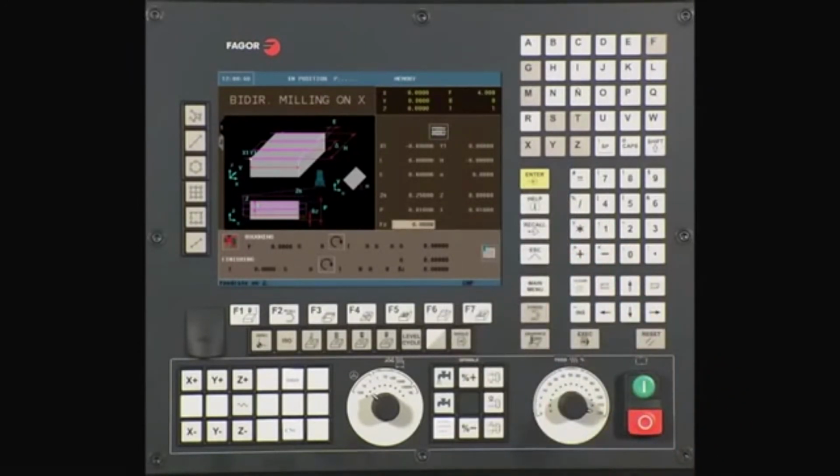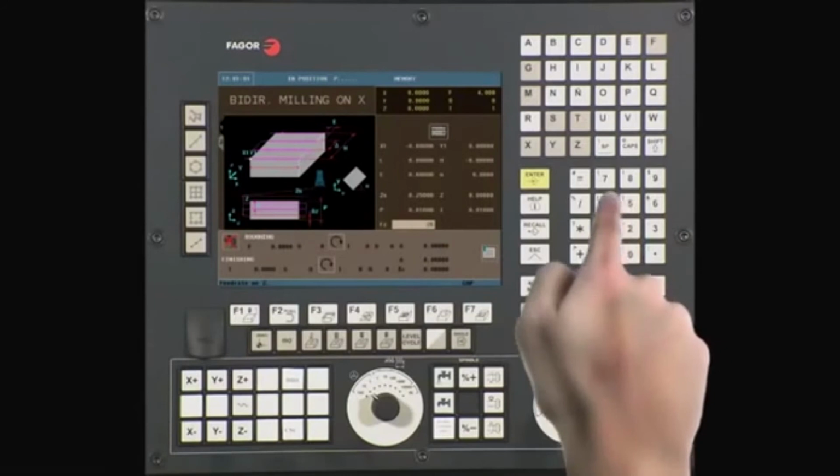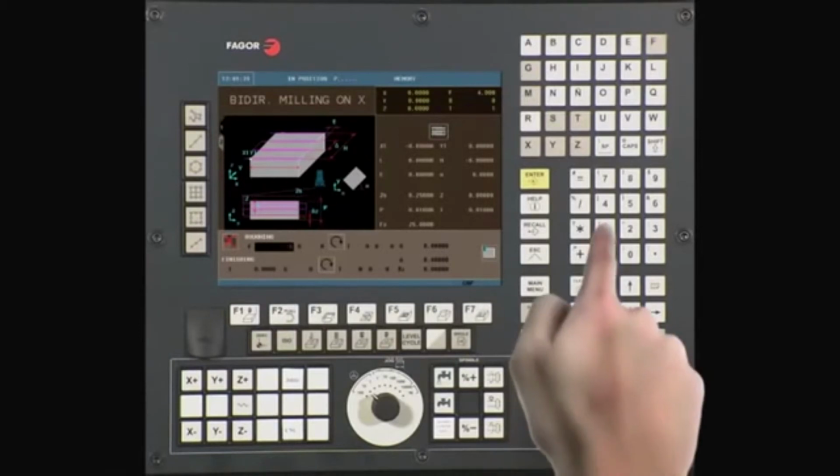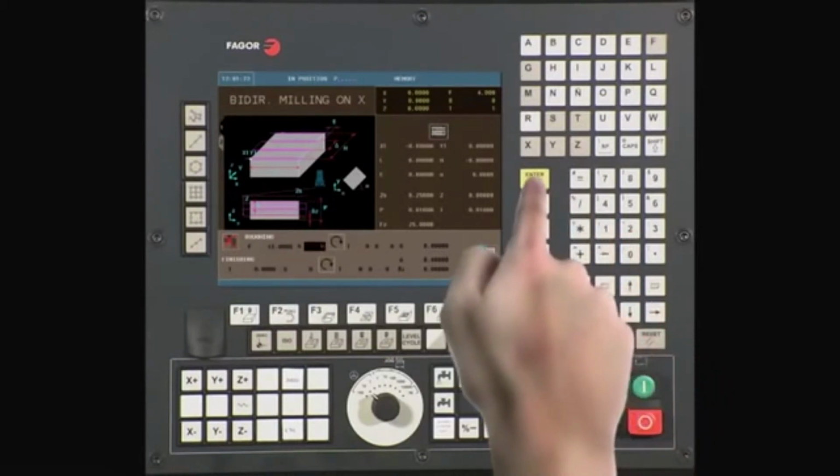FZ. This is the Z-axis plunging feed rate. This value is entered in inches per minute. In this example, we will be using a value of 25. Type 25 and press Enter to continue. Coolant. Use the half key to select if you want coolant off or coolant on during the machining process. Press Enter to continue. F. This is your rough machine feed rate. In this example, we are using a value of 12 inches per minute. Type 12, press Enter to continue.